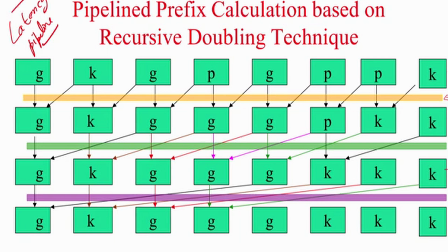The second answer will come off immediately in the next cycle. The third answer will come off in the next cycle, and the fourth answer in the next, and so on, right. So, what is the cycle duration? If I do not have these registers, then the entire computation should happen in one cycle.